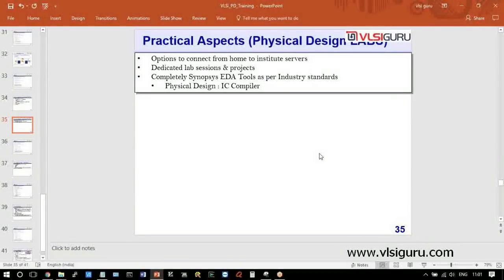But for me as a physical design engineer, after completing it, what is important is, am I meeting 2 GHz? Am I meeting 2.5 GHz? STA, static timing analysis between launch flip-flop and capture flip-flop. That is what it is. For that, setup and hold is very important in physical design and in STA. But when it comes to a layout engineer, setup and hold is not important at all. SPICE input waveform and output analysis of the waveform is quite important, by creating a drain, gate, or substrate for all the nodes and creating a layout.